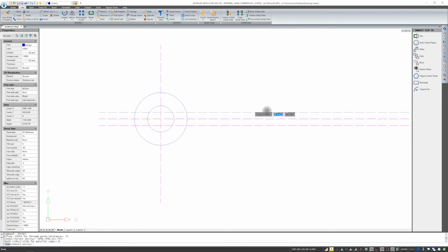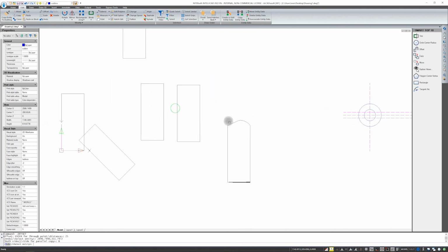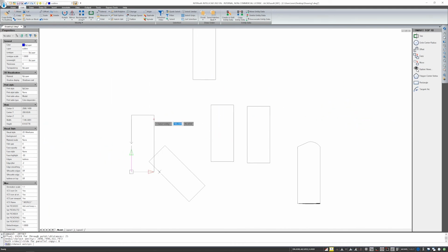I'll go back to my rectangle for a moment and choose the rectangle that was drawn using the line option. I will select one element and say that it should be offset to the center by 25 units, because the program still remembers these settings for us. And now I have to modify each side separately. Now I'm going to do the same with this rectangle that was created as a polyline. Note that the whole thing is selected. If I do it inwards, see how the corners have been leveled.